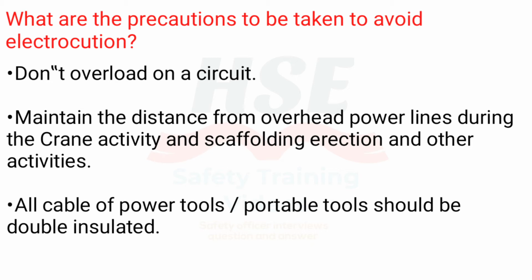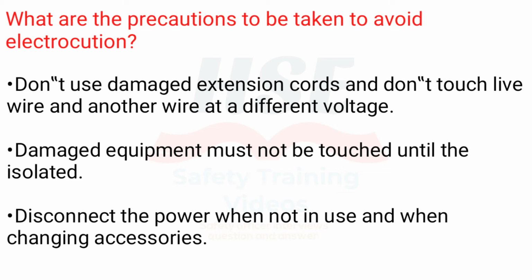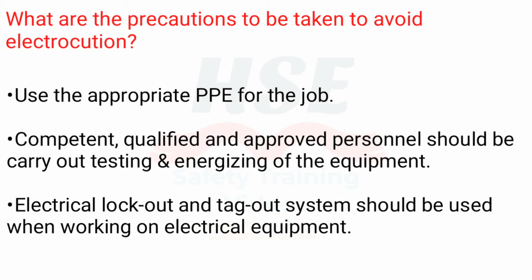All cables of power tools and portable tools should be double insulated. Don't use damaged extension cords, and don't touch a live wire and another wire at a different voltage. Damaged equipment must not be touched until isolated. Disconnect the power when not in use and when changing accessories. Use the appropriate PPE for the job.